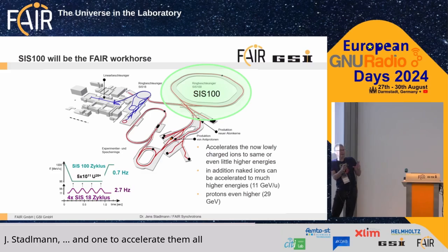Yeah, the individual machine has its own clock, but then there's this centralized White Rabbit system which synchronizes the machines. White Rabbit, for those people who haven't heard of it, is like a PTP standard on steroids. So you synchronize down to below nanoseconds, at the picosecond level.